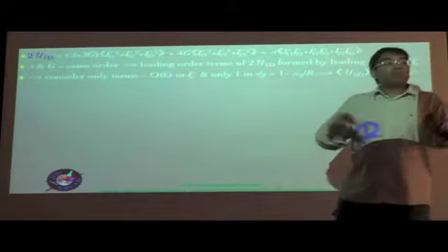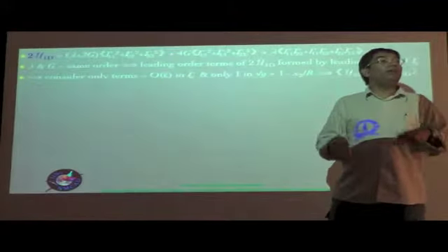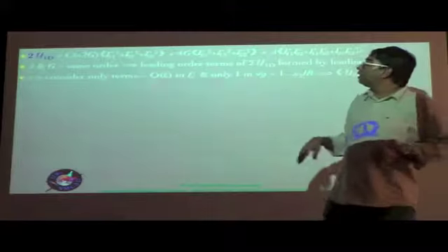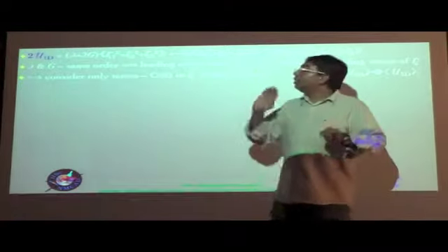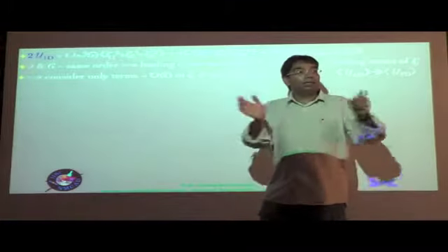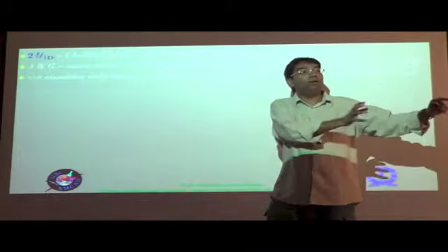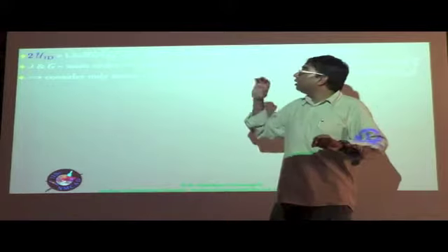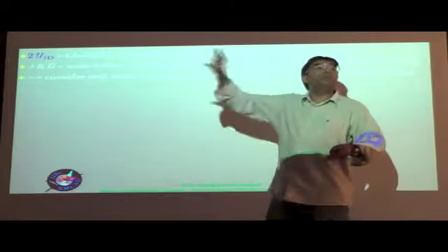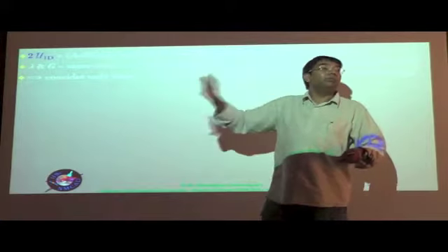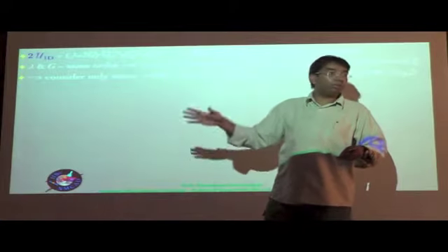But here, because the matrix D that we have is of all the same order of magnitude, because lambda and g are of the same order of magnitude, this segregation of leading order terms and higher order terms can be equivalently made at the strain level itself instead of doing it at the strain energy level. But that is something which is not always possible.